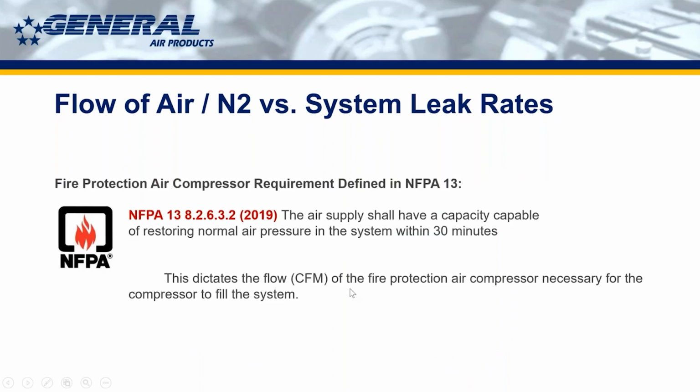This is the section of the standard that refers to the 30-minute fill-up time, and this dictates the flow in CFM. CFM stands for cubic feet per minute. If people aren't familiar with that, I sometimes get carried away on these things. We kind of live and breathe air compressors, so CFM is just a common part of our dialogue. So CFM is cubic feet per minute of air. That's how you measure volumes of air. So this section of the standard dictates the flow, or CFM, of the fire protection air compressor necessary to fill the system.